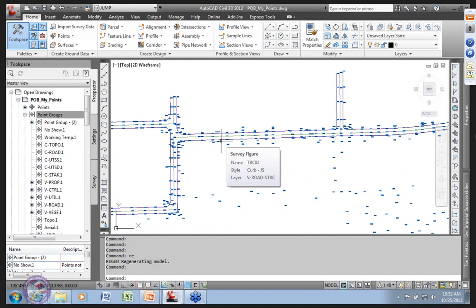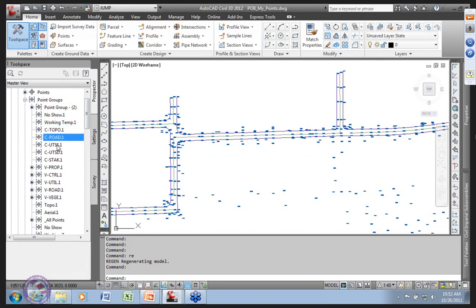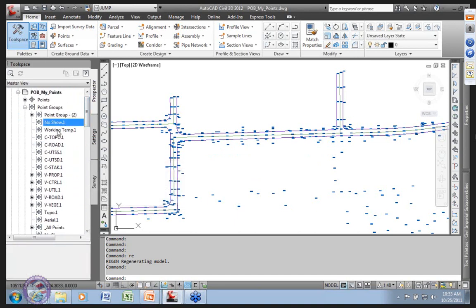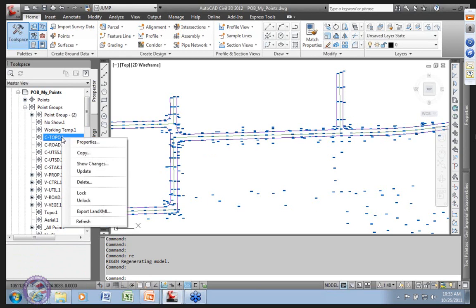Also, I want to make another point here: when I did that insert and explode, that drawing happened to contain a whole bunch of point groups. And why I ended up with the weird labels is because I ended up with all these additional point groups, because I wasn't paying attention when I made that, and it does have point groups in it, and I forgot to pull them all out, right? So now I got near duplicate point groups all over the place, and I got to get rid of these, okay? Better yet, have a better crafted drawing out there, right, without the point groups in it.